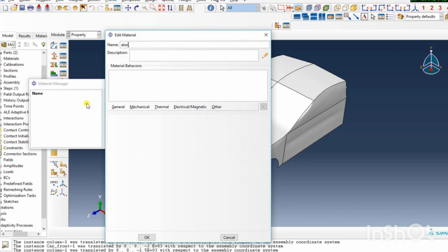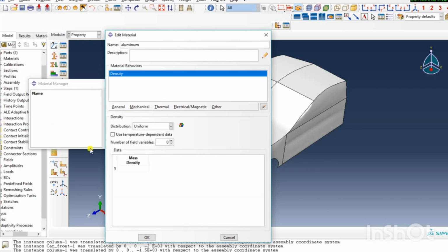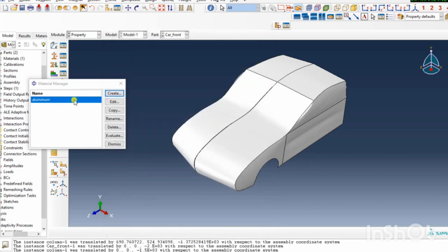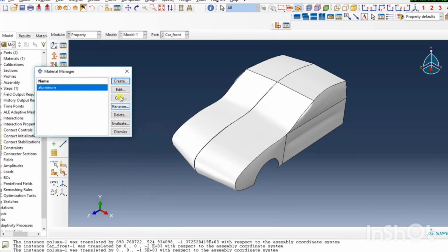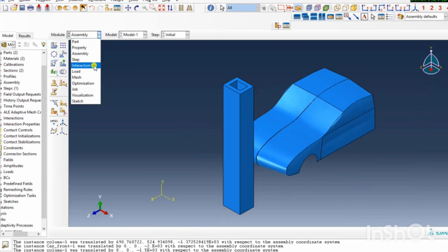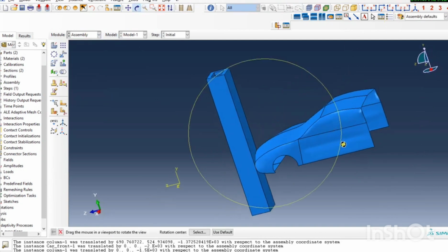For the meshing strategy, we will be using a refined mesh along the length of the column to capture local buckling modes accurately, and we will include considerations like element aspect ratio, mesh convergence, and hourglass energy control. We ensure that artificial energy, that is the hourglass energy, remains within acceptable limits, typically below 5 to 10% of the total internal energy.